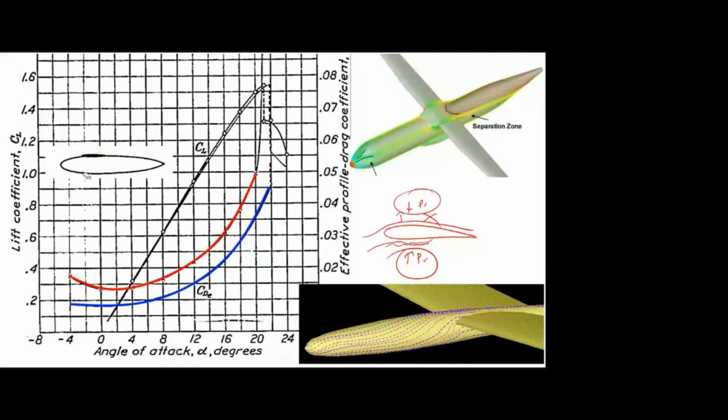So if you take this upper surface, that is a high wing, you can see all this disturbed flow is almost in the bottom surface only. The upper surface is very less disturbed. So this produces minimum drag. The high wing configuration produces minimum drag. So this blue color is only for the wing, and this red color is for the wing plus fuselage combination. You can see for the high wing configuration, the drag is increased, but at least the trend is the same. Okay, the trend is the same for wing alone and wing plus fuselage configuration.